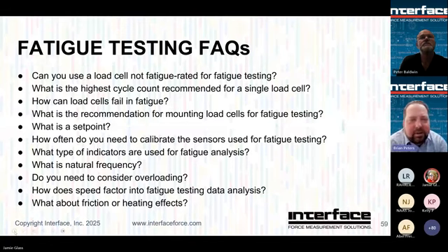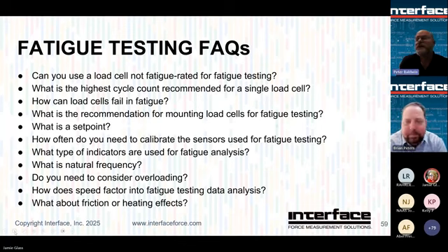All right, so can you use a load cell not fatigue rated for fatigue testing? Peter, what would be your answer on that? The answer is yes, but you need to make sure that your capacities, that SN curve that we discussed earlier, are well within the requirements of what you need for the longevity of the test.